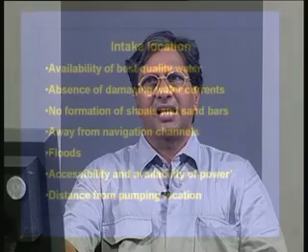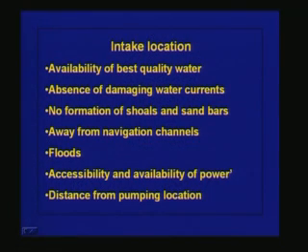We should locate these intakes wherever the best quality of water is available. We cannot locate the intakes where we do not have the best quality or the water quality is very poor. The location where we install these intakes should be protected from damaging water currents. Water currents should not be very swift, such that the dynamic load from the water on the intake structure is significant and it can get damaged during floods.